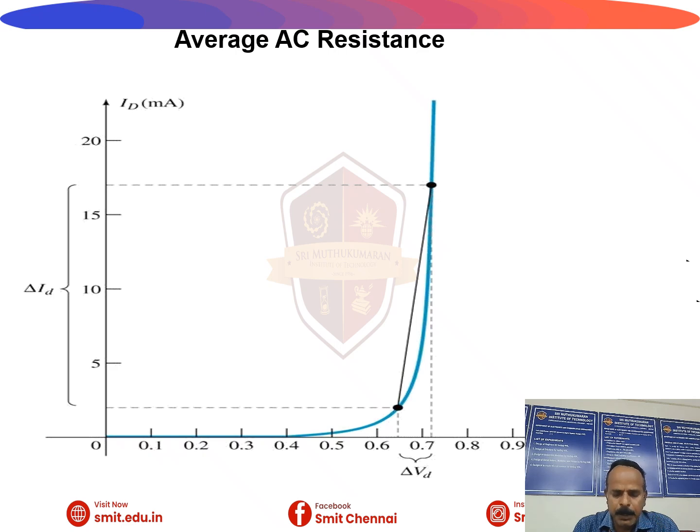Generally, there are two main breakdown mechanisms that happen in a PN junction. One is called avalanche breakdown, the other one is called Zener breakdown. In the lightly doped diodes, the depletion region is very wide. When the reverse bias is increased, the minority carriers gain sufficient energy and collide with the atoms in the lattice, generating additional electron-hole pairs. This process multiplies rapidly and results in the avalanche breakdown.